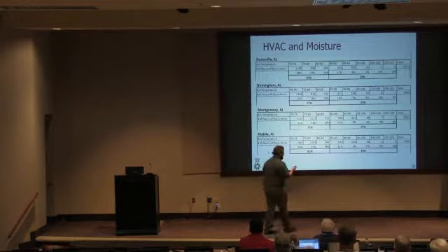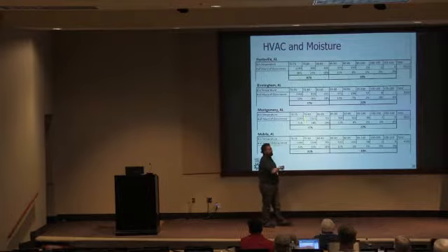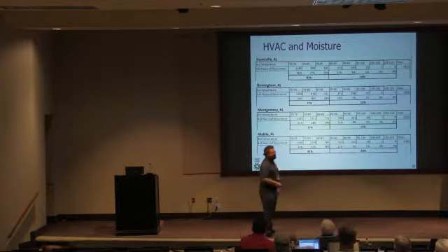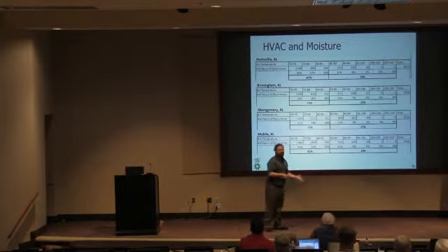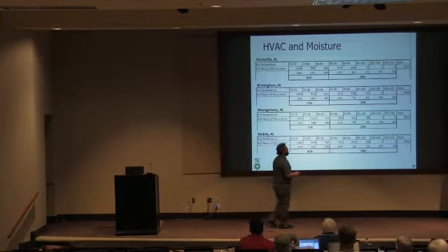But the reality is, you're already oversizing the equipment based on the temperatures that we normally see. And if you oversize even more, you don't effectively dehumidify, and you don't create good comfort. And people don't realize that they're uncomfortable because they are short-cycling their equipment and they're hitting set point too fast.